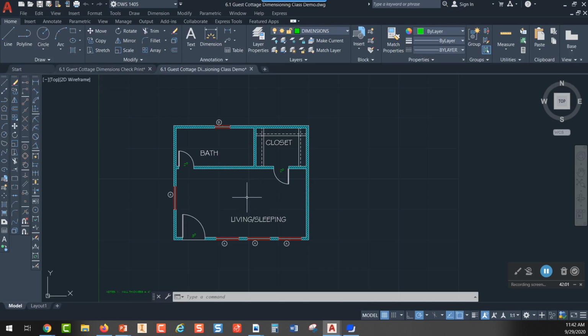All right, so now look on page 314. And on 314 and 315, you're going to see all your dimension style settings. So there is a video in Blackboard that leads you through setting up all of your dimension style for this project. And so it's in those style settings you're going to set up your text height and your arrow or your tick marks instead of arrowheads.